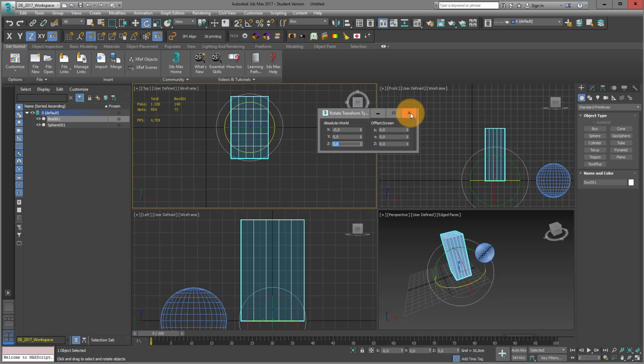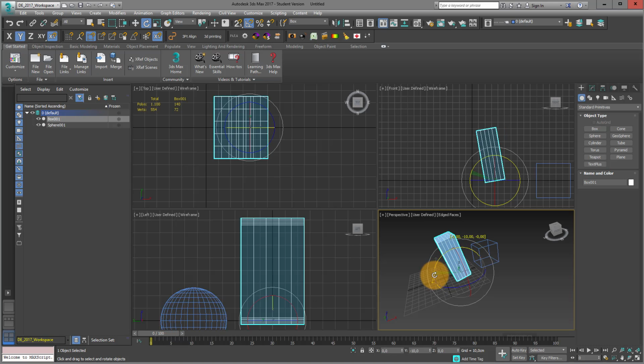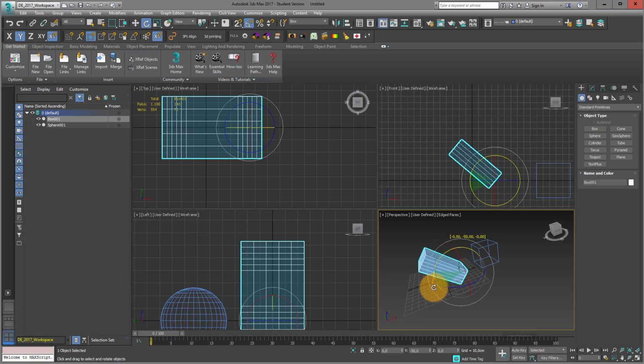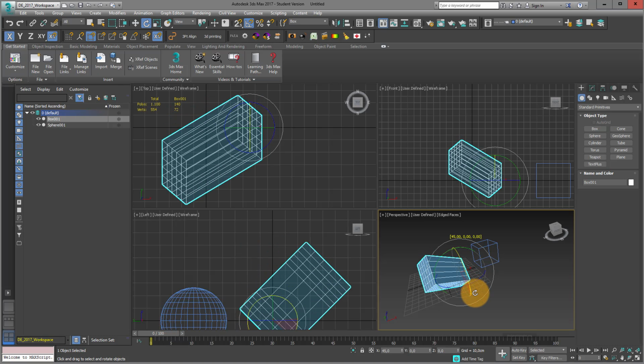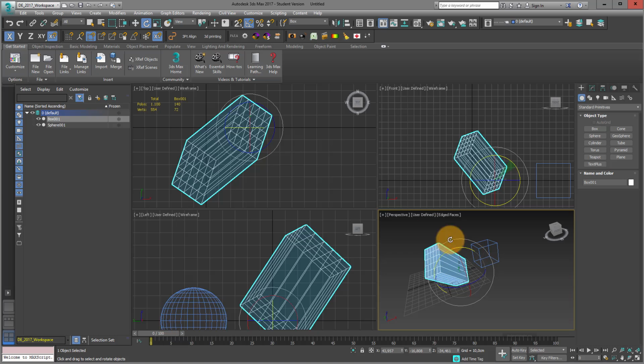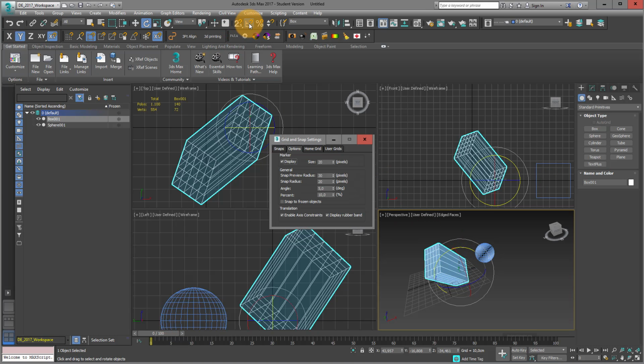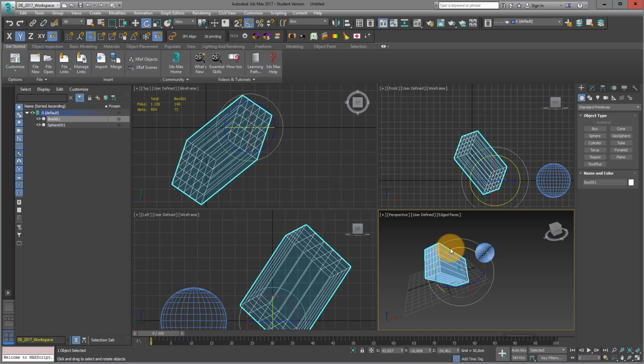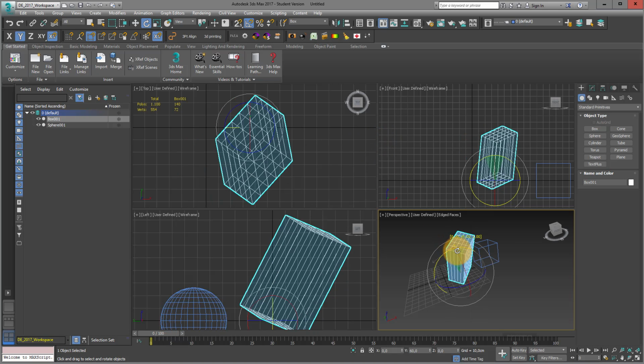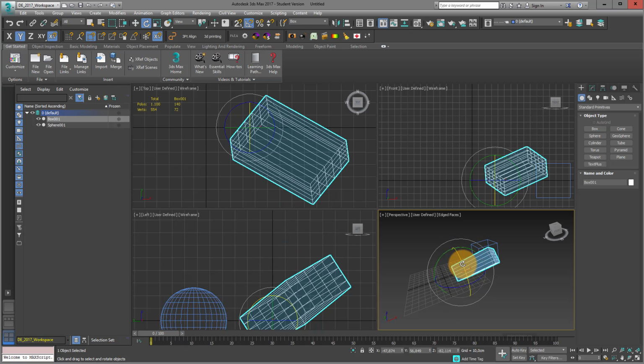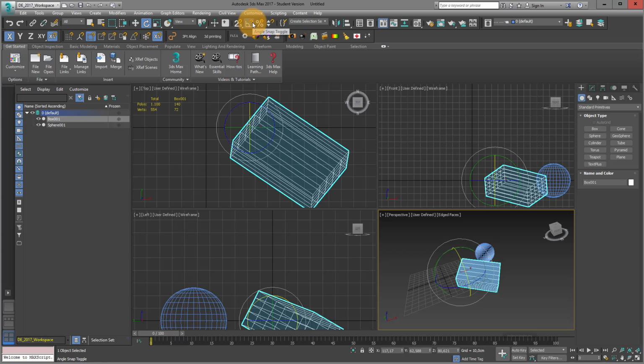When I rotate objects, I mainly or quite often use the angle snap. The angle snap has the advantage that you move in steps, in this case of 5 degrees. So it's a better way of how to control to move the object. You can also change it with right mouse click and then you can change the angle snap and just say you want to have 15 degrees, which is probably quite something. So you can just see that it just moves in big steps of 15 degrees. So if you choose rotate, be aware that you can do it precisely.